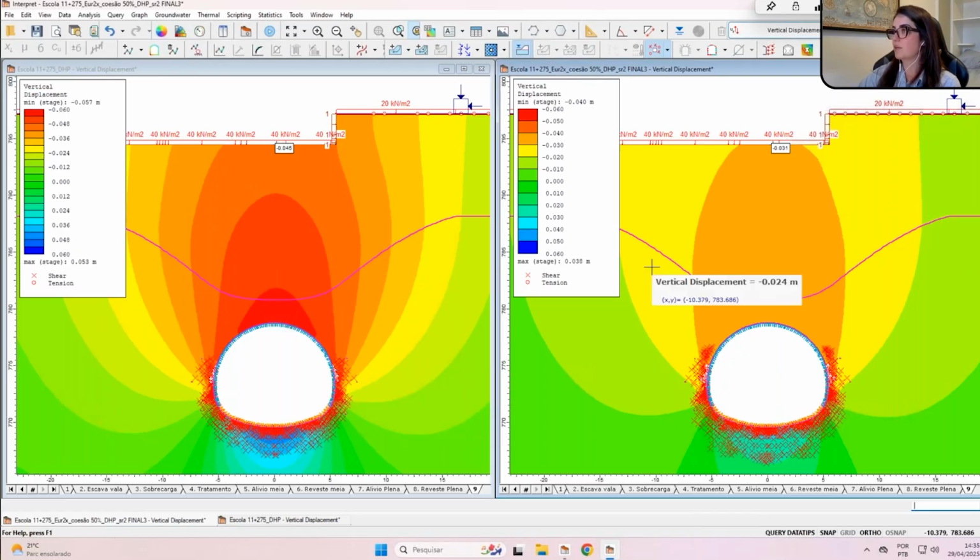And on the left, we have a model with unloading modulus and residual parameters with a lower cohesion. Because we changed the residual parameters, we have an increase in the yielding. But as we work with the unloading modulus, we have a decrease in the settlements. You can see here 45 millimeters, and here 31 millimeters. So this is very nice when you need to adjust your settlement.